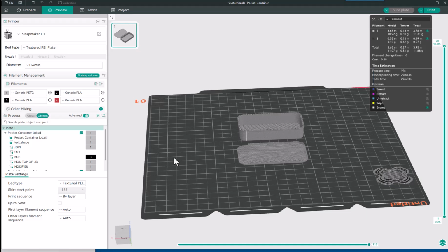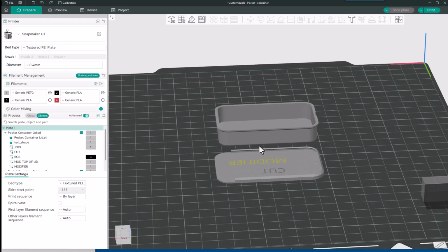how to edit your scale, your STLs, because when you actually scale an STL, like if we just went to this STL and we hit scale, so if we select it and we go up here and we hit scale, because say you wanted to make this a much larger box, like 70 millimeters or something, and you hit scale and you just start lifting up on it, and that's great.